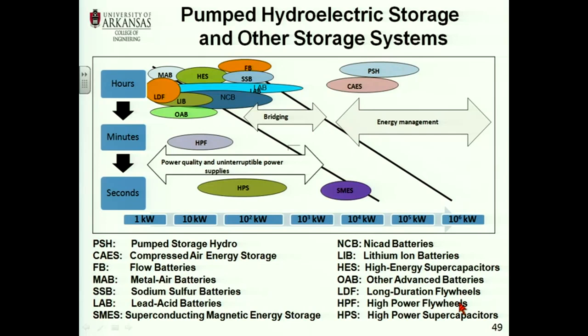So what is the energy if now the voltage drops to 1/2? It's V divided by 2, squared. What is that? V squared divided by 4, right? So that's the reason why the regime that you normally use for the ultracapacitors or supercapacitors is from rated voltage to 1/2 of the rated voltage. And so you need some power electronics, a DC to DC converter that makes the step up, right, that interfaces with a constant DC bus.